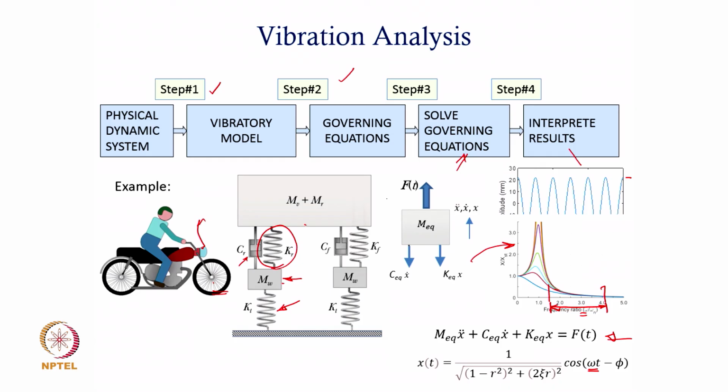Okay. And then of course, I need to also understand and ensure that the suspension at the front wheel is of a different nature or character as compared to the one at the rear wheel. So, obviously, the properties of these springs and dashpots would be different at the front and the rear side, and therefore, it makes sense to model them individually through the individual wheels here. That will give me a much better and more accurate picture, and I will be able to capture the dynamics more appropriately than what I possibly could in the previous case.